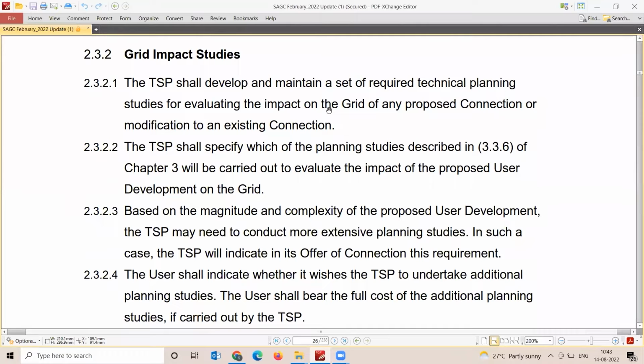Grid code compliance and grid impact study: the same 500 megawatt I am connecting in India, which has 400 gigawatt installed capacity. I am connecting the same 500 megawatt solar plant in an islanded system in Australia, which has only 2,500 megawatt installed capacity. Do we think that my requirements will be the same? Definitely not, right? Why? This 500 megawatt, 0.5 gigawatt added in the Indian grid is hardly anything compared to the existing installed capacity, but in a 2,500 megawatt system, adding 500 megawatt solar is like 20%, right? So your study varies depending upon what the existing system is and what the capacity of the proposed equipment is.